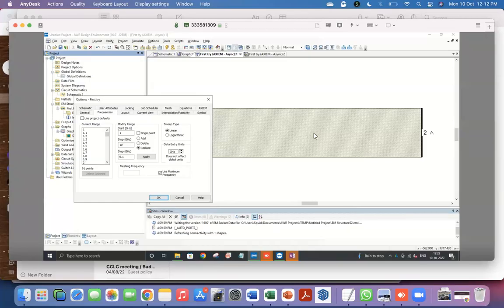So what Microwave Office will do, as long as the frequency range is within the total range. What I mean is, in this example, 4 to 5 gigahertz, you can go to a small frequency range like 4.5 to 4.55 and have 100 points there. It will basically interpolate the data it has and recompute it just from the existing data.